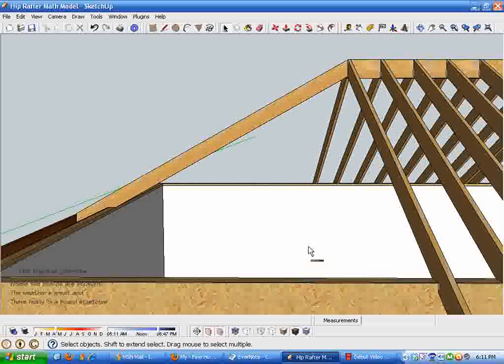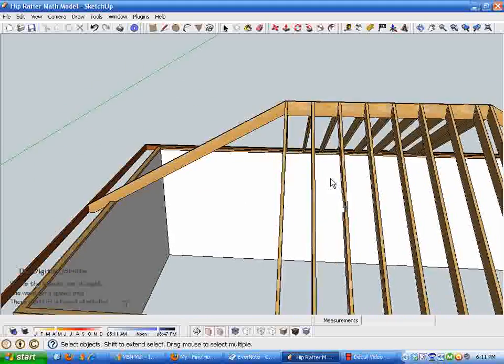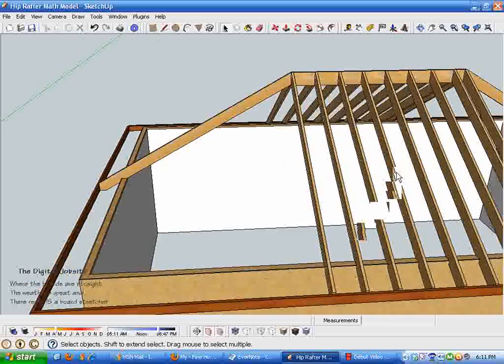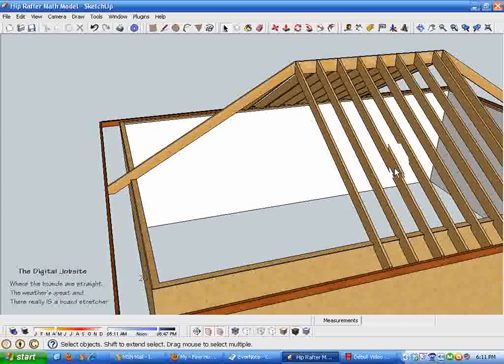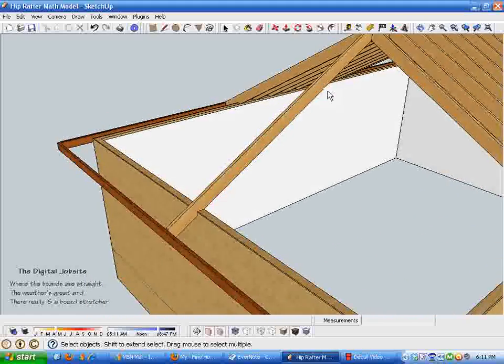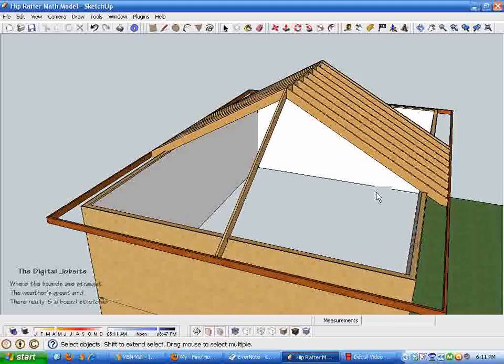that dialog box. And for any hip roof, the main structure prior to installing the hip rafter is the common rafters that make up the basic part of the roof, and then there's one common rafter in the center of the hip on either end, and then the hip structure fills in these corners.